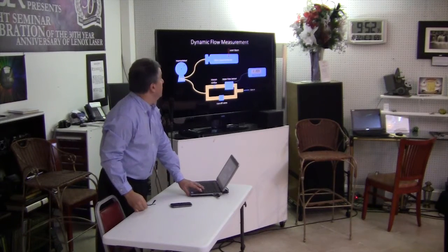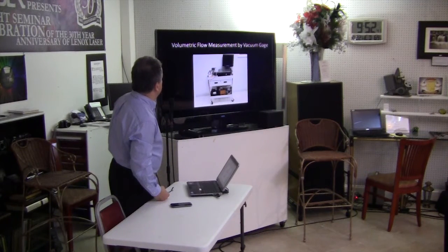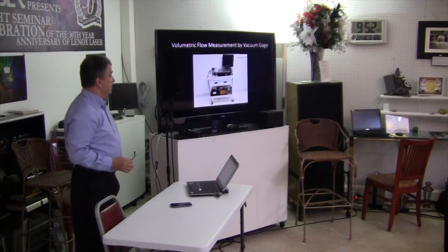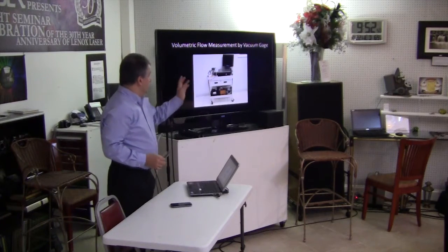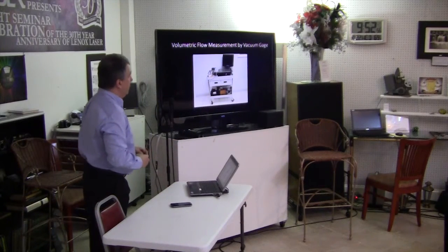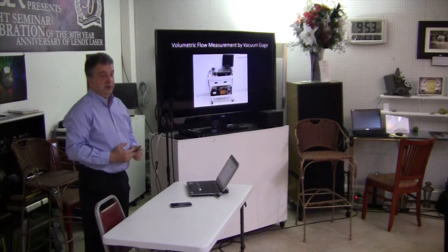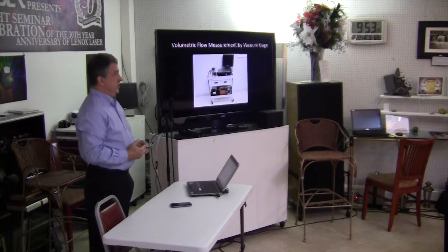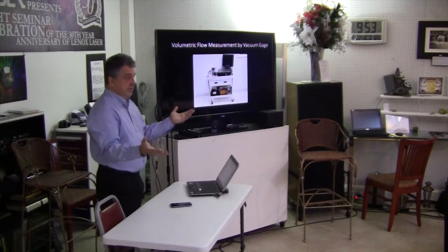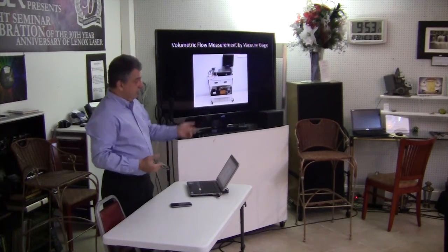So that instrument came from the first one. And this is one of our other volumetric flow measurement instruments. I will show you those. We have tons of those pretty much next to every station. It's sitting on the floor. There's a vacuum pump and all other components. The idea is we measure the deviation in pressure. If there is a leak, we calibrate it with a known orifice. It goes to the steady state, nothing changes. Then we open the leak up and we look for the steady state again.